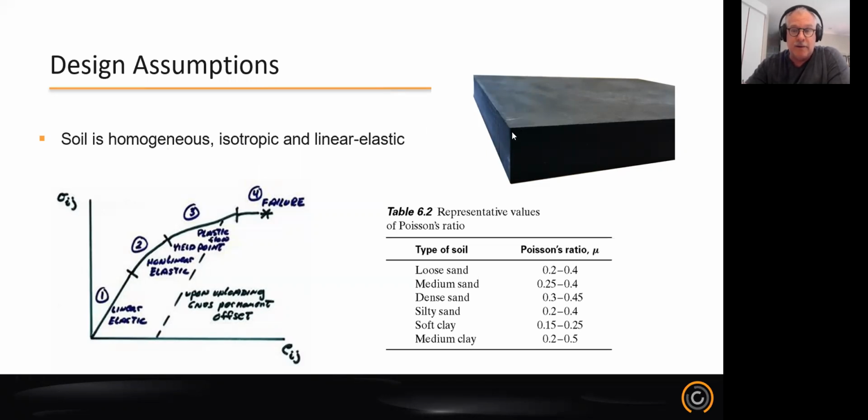And if I squeeze it down in this direction, it will move out in the horizontal direction, and that's the Poisson ratio. So we're going to have to assume a Poisson's ratio for the material. So if we have layered type deposits, or if we have a stiff soil over a softer soil with respect to depth, we're going to overestimate the amount of live load with respect to depth. So these are assumptions that are always done on this side, and they're on the conservative side.